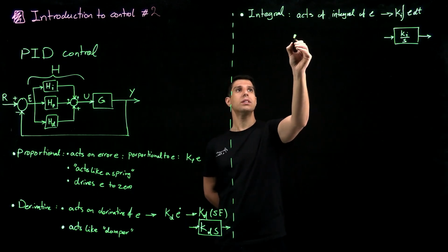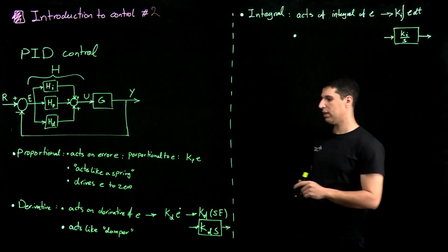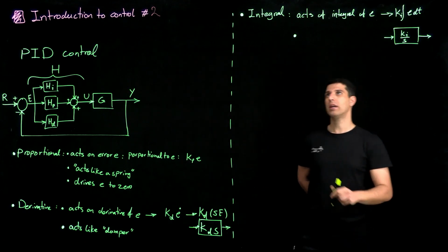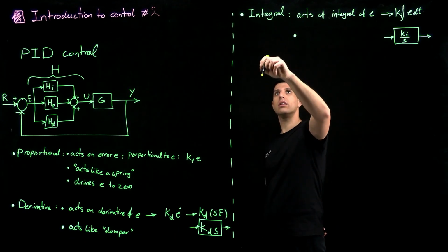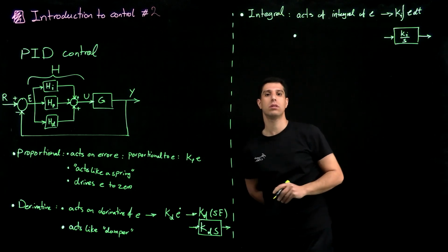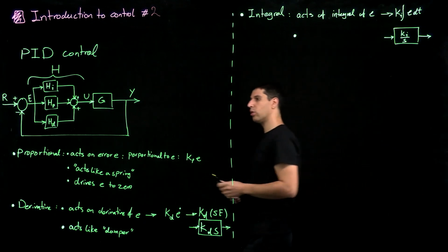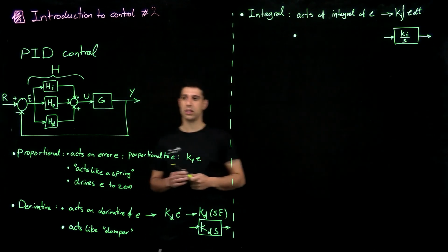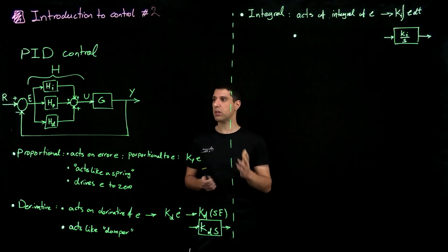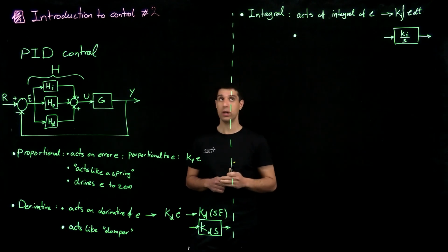What it does to the behavior of the system is a little more difficult than these two on their own, because when we have an integral, this is an ugly integral, it actually increases the order of a system. So for instance, in our pendulum problem, it was a second order system because it was 1 degree of freedom. It had inertia, second order.